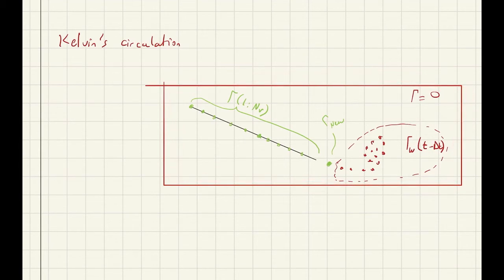So to write it down here, if gamma at t equal to 0 is equal to 0, and via Kelvin's circulation theorem, we know that d gamma dt of a system for all time has to always stay constant. Thus, the circulation of a system stays constant, and thus the d gamma dt is always equal to 0.